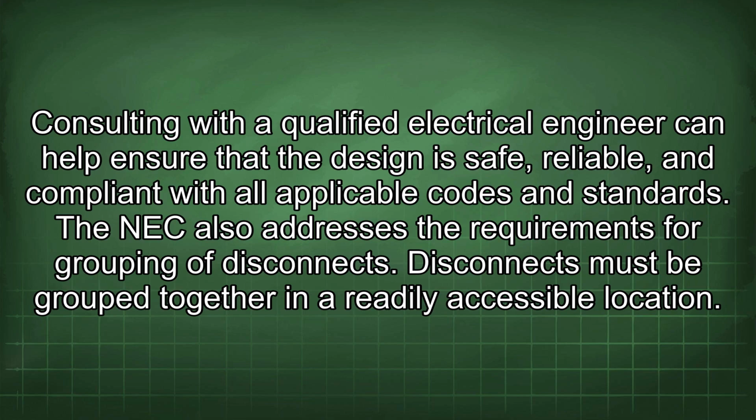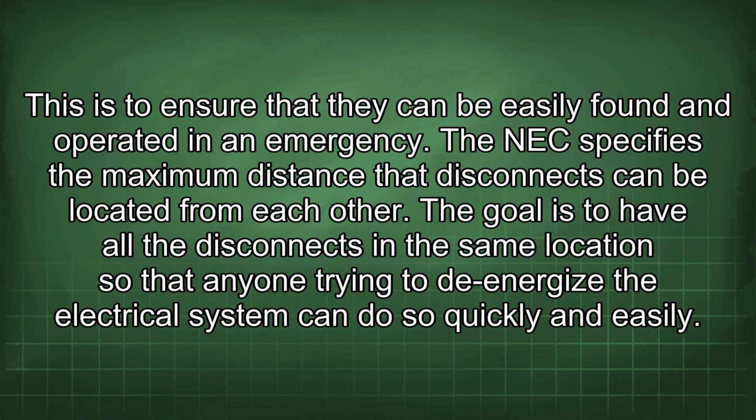Disconnects must be grouped together in a readily accessible location. This is to ensure that they can be easily found and operated in an emergency. The NEC specifies the maximum distance that disconnects can be located from each other. The goal is to have all the disconnects in the same location so that anyone trying to energize the electrical system can do so quickly and easily.